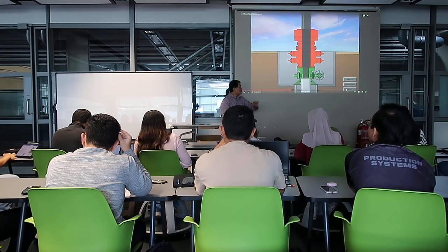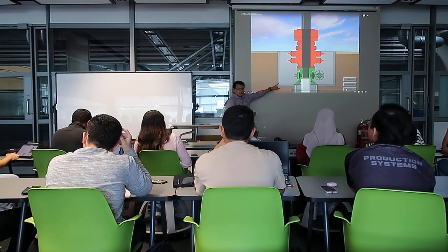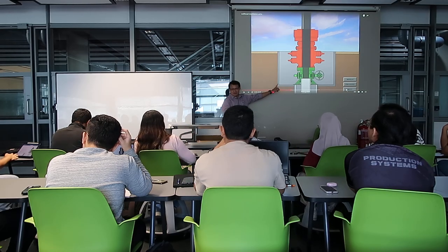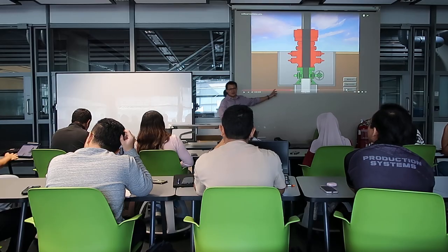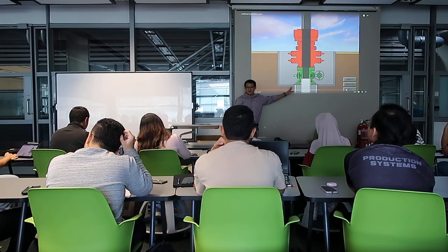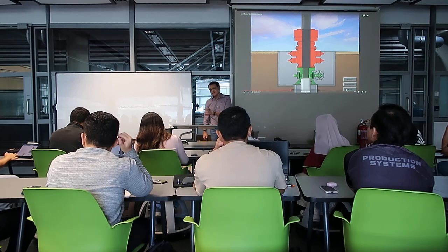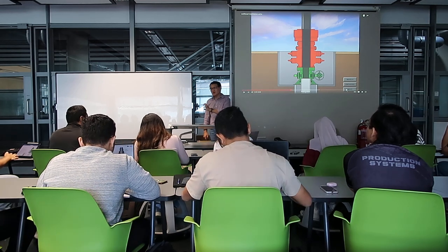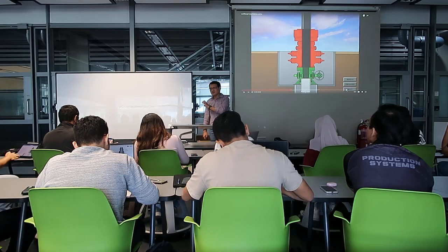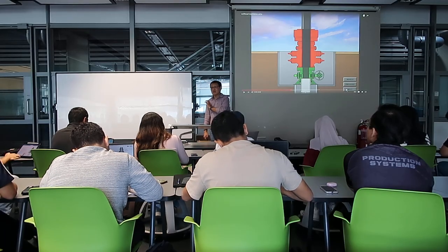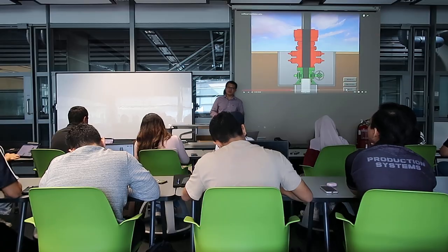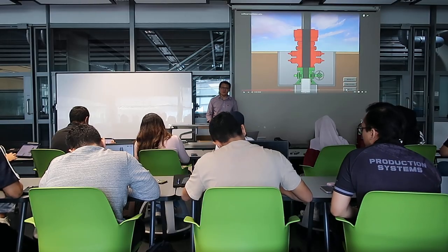It's only when you put it on this wellhead, this connection, you need to test. So this is probably half an hour. When we talk about this test, when we put this BOP on the wellhead, half an hour, just the connection test. So that's what we mean, the BOP test is actually really the connection test here. So just don't confuse. I think sometimes we miss out as well.